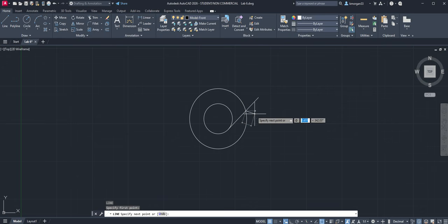And then of course this time we will do @3 and then less than, we will turn 315 degrees. After we turn it, of course, we can cut the line. So this is your final drawing. It should be finding the intersection, and drawing with relative positions, because we want to draw relative distances from the click point. We start with this point and then do the second point like this.